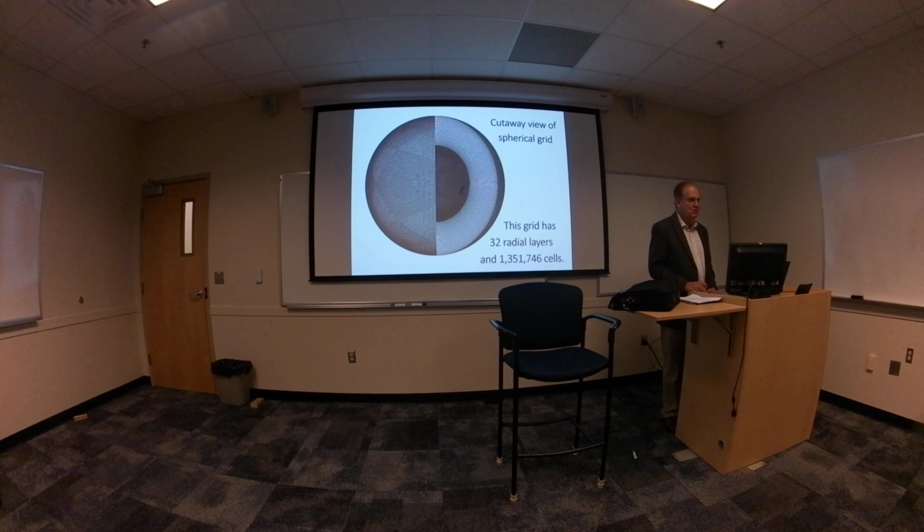Change the resolution, you double the resolution, and see if you get an answer that's very similar. If you get a big change, you make all the cells half as big, and you get dramatically different answers, you know that you didn't have enough resolution in the first case. So that's almost always an issue. Are you adequately resolved?